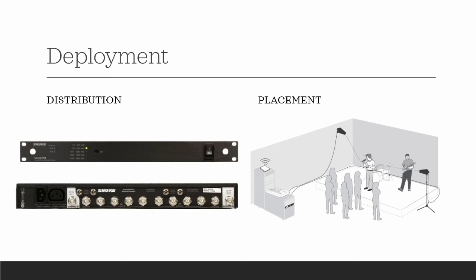The other thing we want to note is that the features on our stage, if this is a stage type setup, can also block our RF and block our path to our antennas. So we want to make sure that things like drum sets, things like keyboard rigs, where there's lots of metal in them, those also will block RF. So as we do our stage design, that's definitely something that we want to think about.